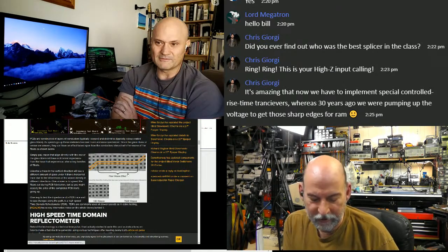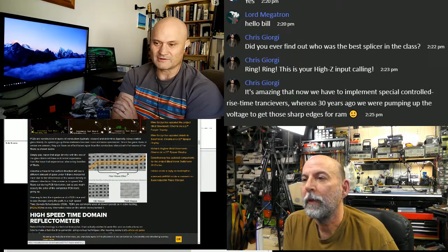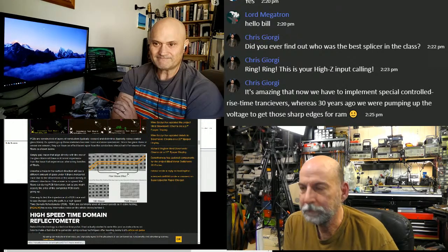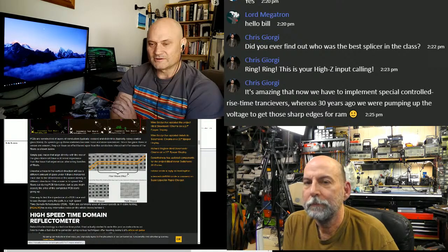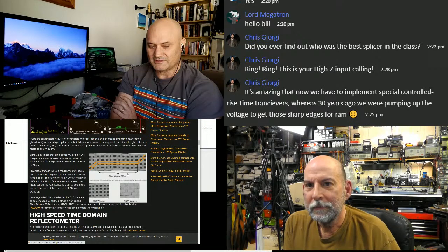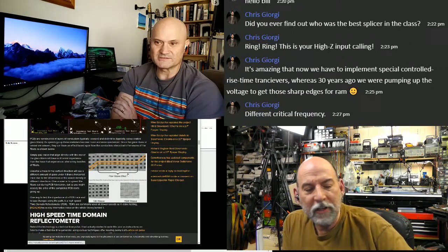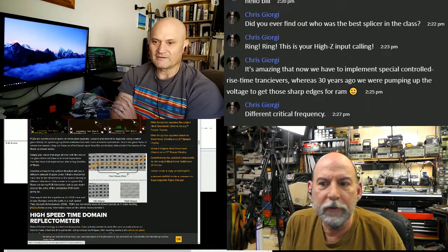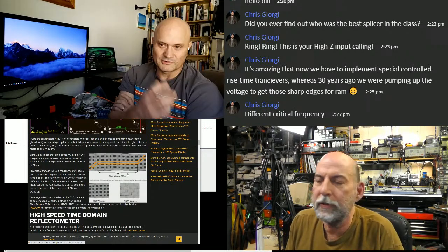Too fast. Yes, too fast, probably. It all got too fast. The die shrink actually increases the speed of the output drivers, and that creates noise. Created noise and ringing. Failed EMI testing. Fast isn't always good. Sometimes you can get on a data bus too fast.